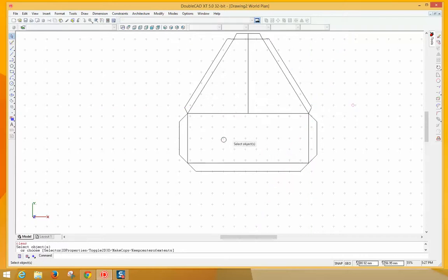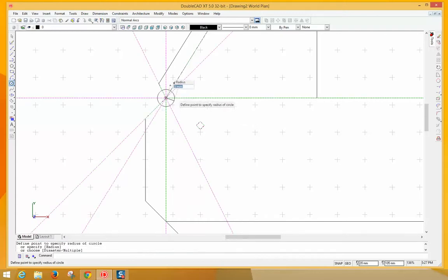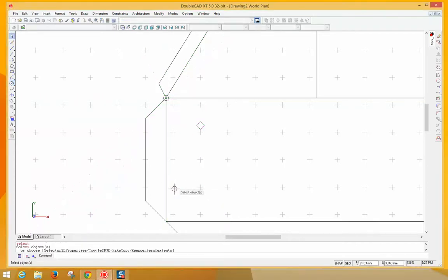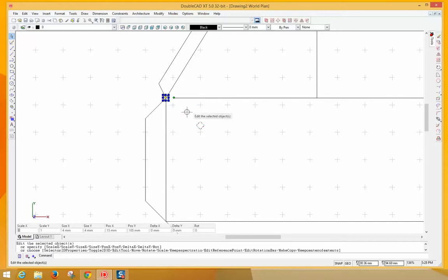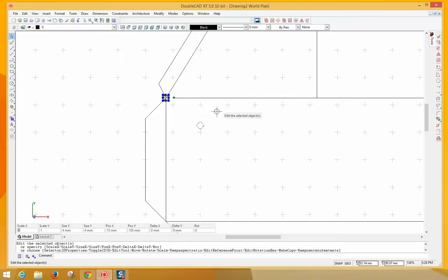And whenever you fold sheet metal, it's nice to have a little slack in the corner so they don't pucker up. And the way you do that is you put in circles. Notice it says radius. So if we want a 4mm hole, we put a 2 radius. Enter. A couple of ways to do this. One is you can copy and paste this. Okay, let's select circle, right click, the usual copy and paste tools.